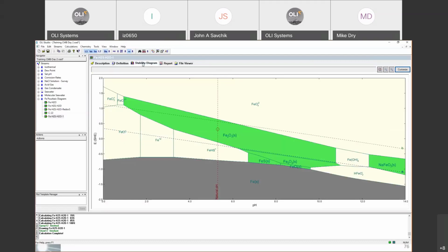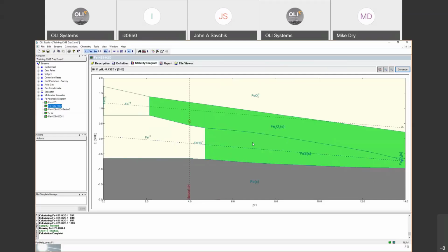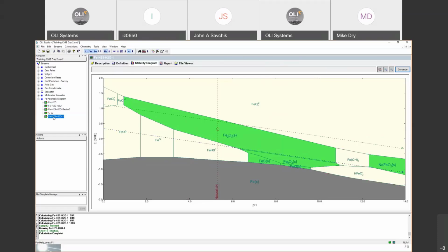Now it's, again, different. The pH is low. Everything continues moving to the left. The area of stability for iron sulfide is small. You remember that at ambient conditions this area was huge, a very wide pH range and a wide range of potential. But by increasing the temperature to 250 and the pressure to 60 atmospheres, that area is now very small. So if I go back to conditions with high pressures and high temperatures, I shouldn't count on the formation of iron sulfide as a protective layer, because if it does form, it forms at high pH values, above neutral pH, and it's a really small area.